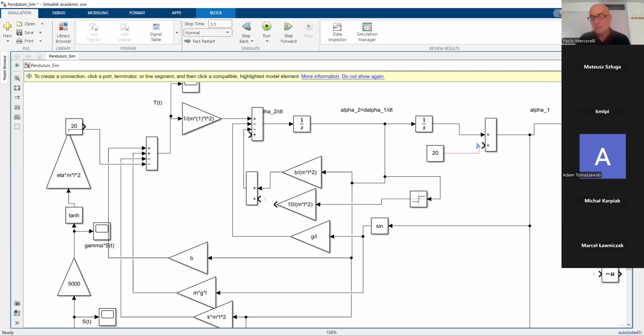And let me make the last very important consideration: considering a disturbance directly in the output. This means we have something which disturbs the position. Of course, this is not extremely realistic, but it can be considered. Typically, we have a disturbance at the torque level. But in any case, if I am able to overcome this disturbance here,